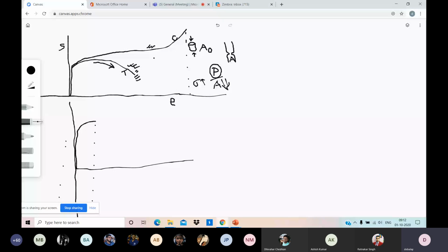So you can see the difference that I am drawing here. In tension, I am showing fracture here. In compression, I am showing fracture at a much higher strain. Will it be true or not? Will that happen or not? For ductile metals? Yes, sir. That happens. So suppose steel, I take a normal mild steel, you will get say elongation to failure 25%.